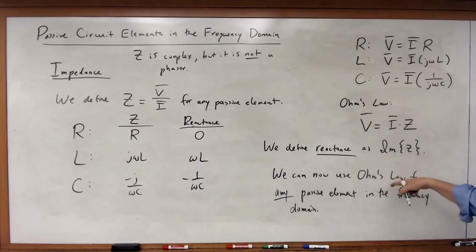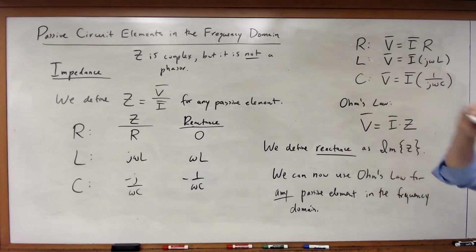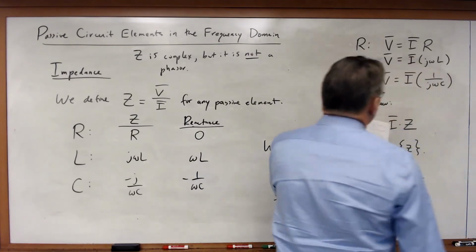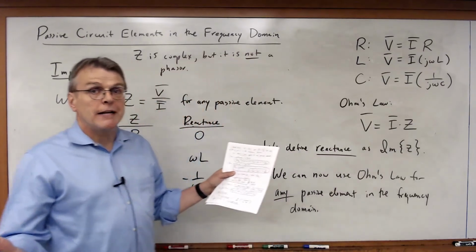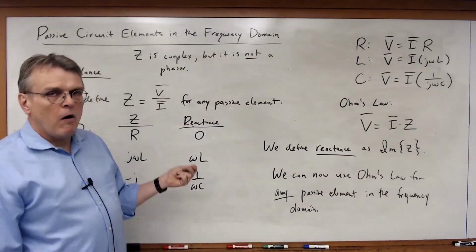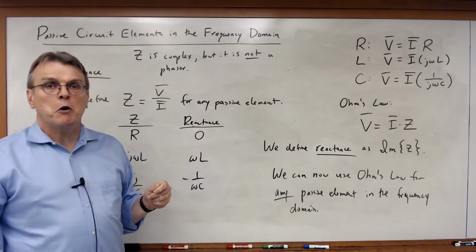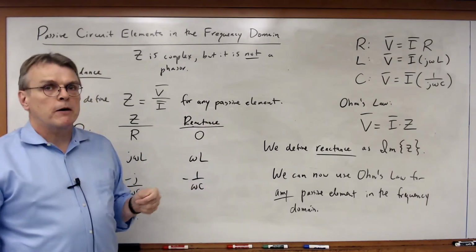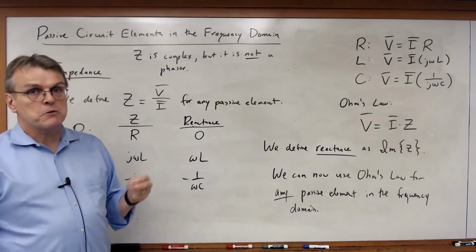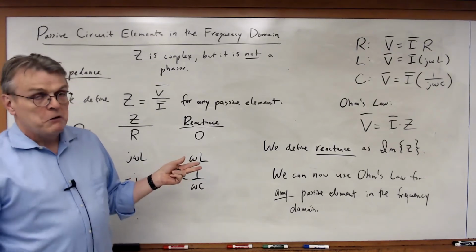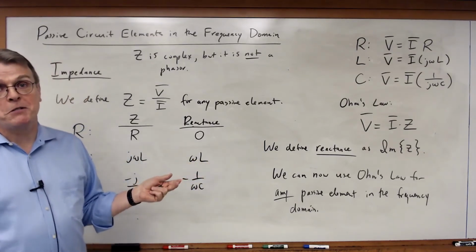So here is a real powerful use for this idea of impedance. It now lets us treat everything the same. All passive elements, we're going to be plugging them into Ohm's law as long as we're operating in the frequency domain and using phasors and complex numbers. Turns out that's going to be extremely useful to us, as we're going to see.